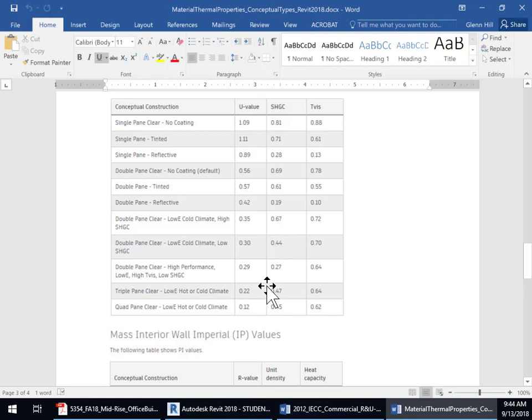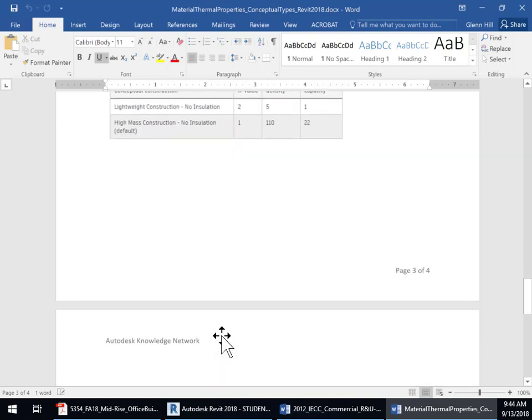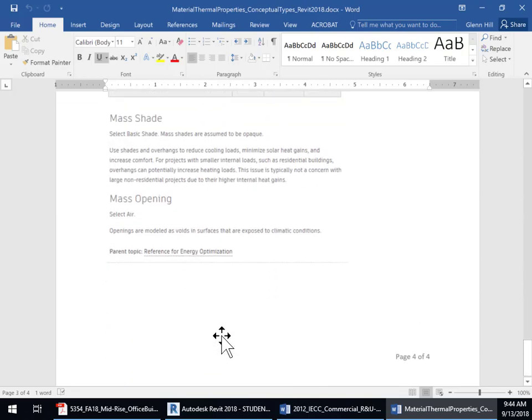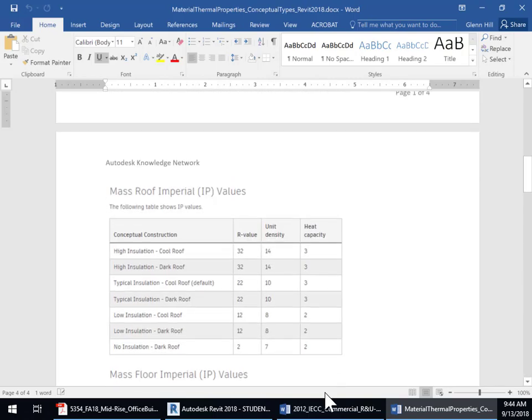That meets the solar heat gain coefficient, but this is a lot more insulating window. We need a 0.46, and of course in U values, the lower the better instead of the higher. This is 0.29, so we're just going to use this one. High performance, low E, yeah, that's got at least the solar heat gain coefficient that we need. Okay, and then the interior walls, mass skylights, and so that's going to be it.